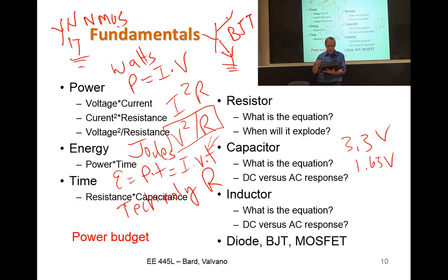Impedance, right? In other words, how much current goes into the base? Bunch. How much current goes into the gate? Virtually none. Impedance went up. Power goes way down. This is why all our digital logic is done with MOS field effect transistors.